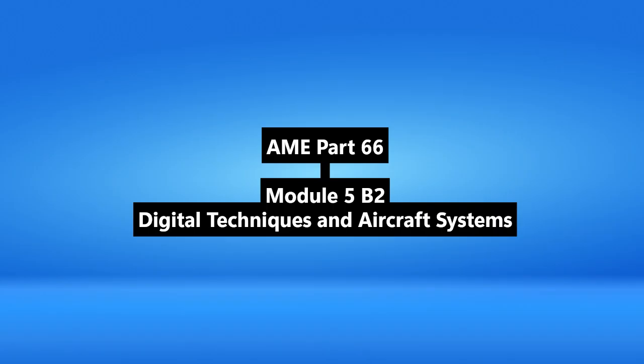Hugely heavy, complex, so many potential failure points. Nightmare to troubleshoot, I bet. You bet. Digital data buses changed all that. They're basically shared communication highways. Multiple systems can connect to the same bus to send and receive data, drastically cutting down on wiring, weight, and complexity, and improving reliability. Data travels serially, bit by bit, along the common path.